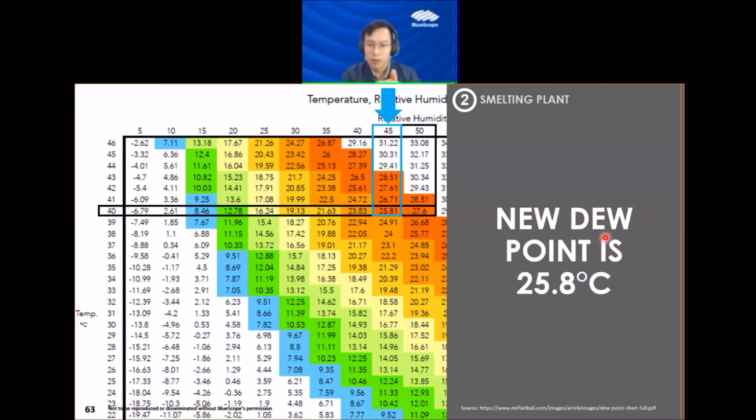And just now I did mention that for a smelting plant, if the roof starts leaking, what will happen? The place where it will start leaking first will be right above the smelting furnace, because it's the hottest. So you have leakages during the rain. And imagine drops of water keep dropping onto the furnace and onto the molten metal, then you have a scenario of spattering molten metal almost all the time, if not, during the rain.